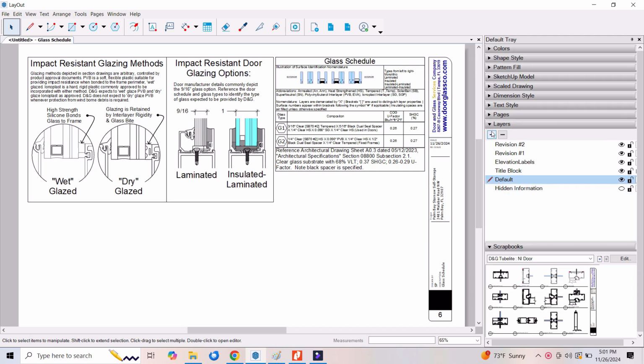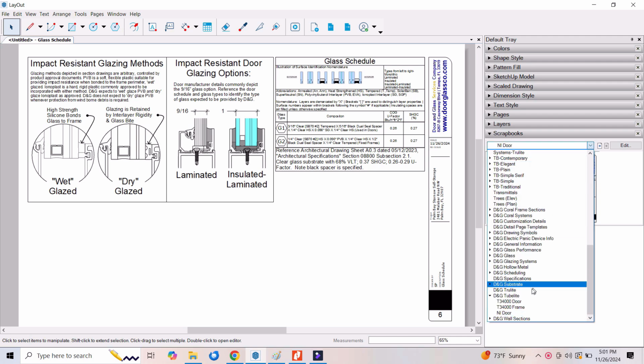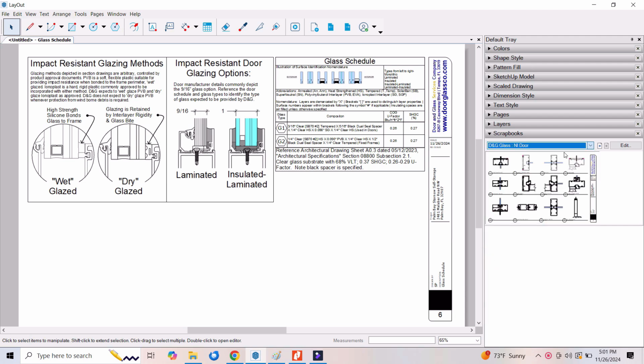Normally we're going to have a sense of what kind of glass we need to use on the project based on the energy values, what's required. We go to D&G glass. This has a bunch of different performance, center of glass, solar heat gain values for various different types of glass that we commonly use. Of course, in this little side panel, you can't read them at all.